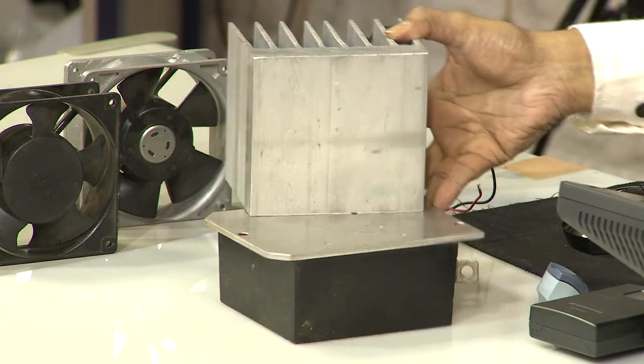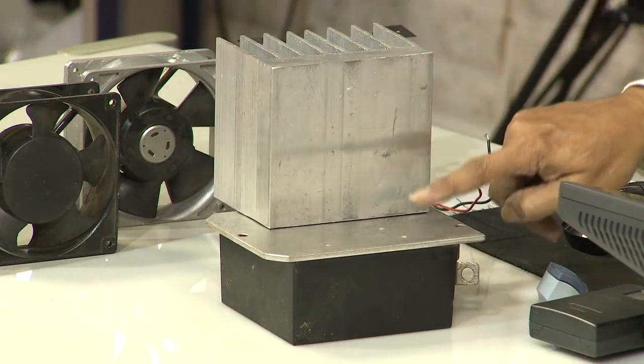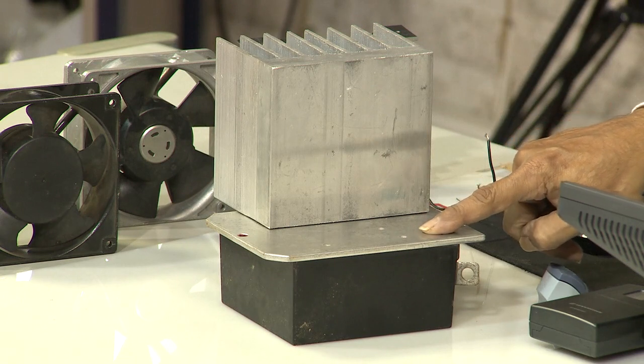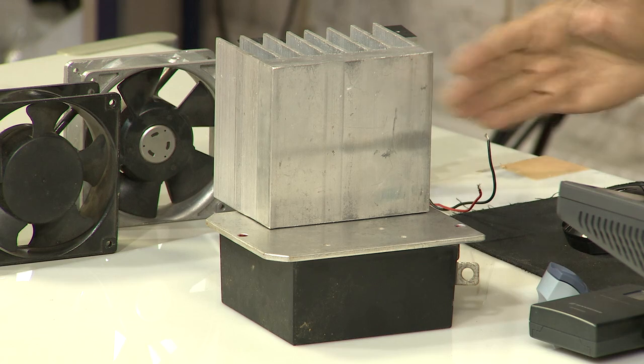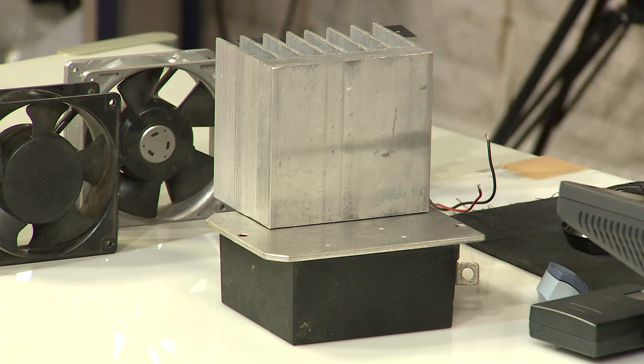So, I have a surface, you have a surface, and what all you have spoken about, saying keep the surface at a temperature, still tremendously depends upon the resistance, the air gaps and the contact that is made. You have hills and valleys, then you have an RMS value of the roughness, and then when you mount one over the other, how well they behave. This is all related to that.